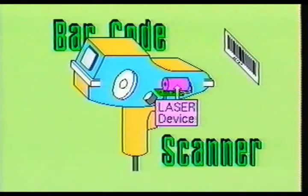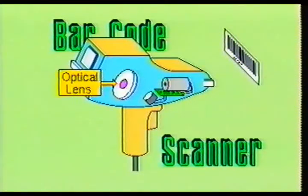Inside the barcode scanner, you will see the laser device, which may be a helium-neon gas laser or a semiconductor laser as shown here. You'll find a set of optics which will contain a lens and a focus lens. The larger lens is used to focus the returned beam back onto the photodetector. The focus lens is used to maintain the correct beam size for the scanning purpose.